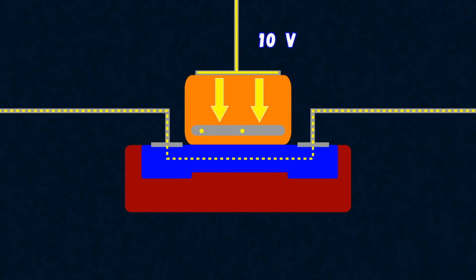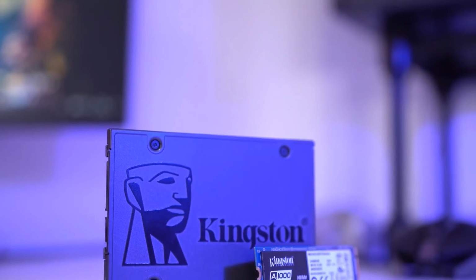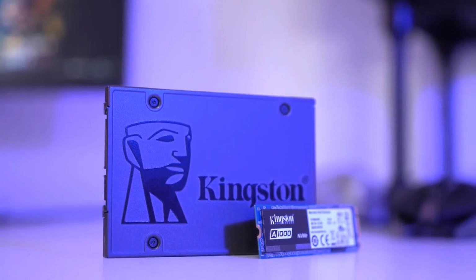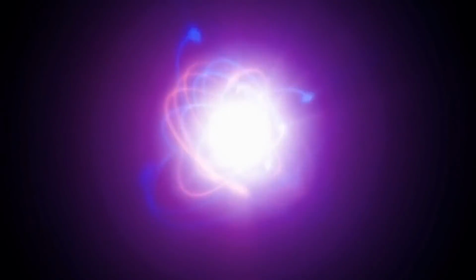More about the tunnel effect, by the way, we had a separate video, the link to which will now appear in the upper right corner of the screen. And in this case, thanks to the fact that we applied a large electric field, some electrons from the channel will be able to tunnel into the floating gate, filling it. And since the tunnel effect is a purely quantum mechanical phenomenon, not having an explanation from the standpoint of classical physics, it can be said that familiar flash drives and other similar media are a vivid confirmation that quantum mechanics works, no matter how strange its laws may seem to us at first glance.